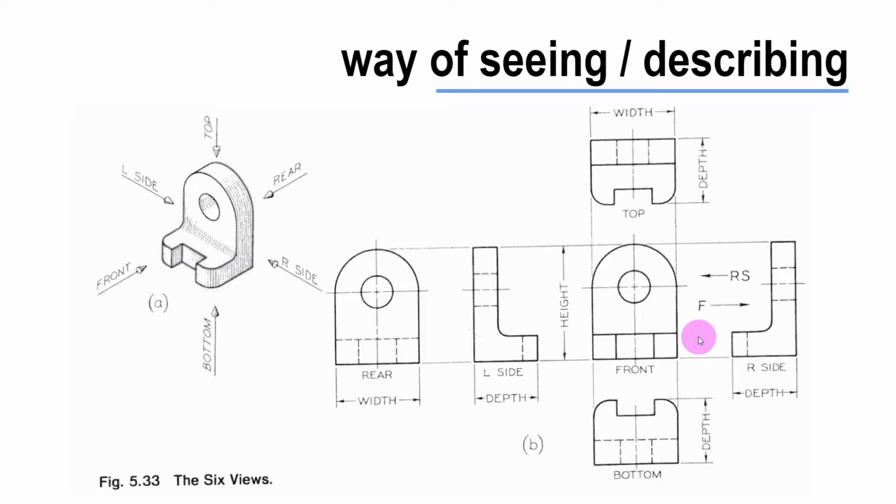Hidden lines aren't necessarily always present in every single object. It just depends on the object being described and the features that it includes. And same thing with center lines. If an object has a curve, then a center line would exist, but if an object doesn't have curves to it, then center lines wouldn't be necessary.